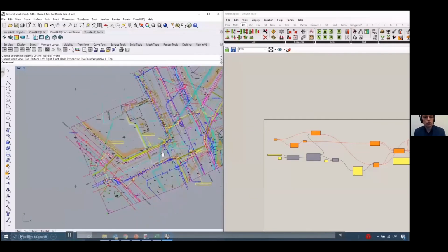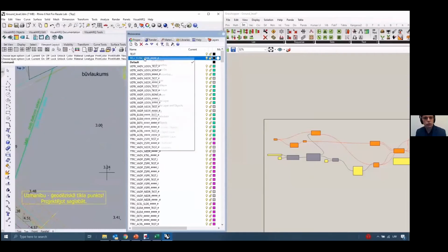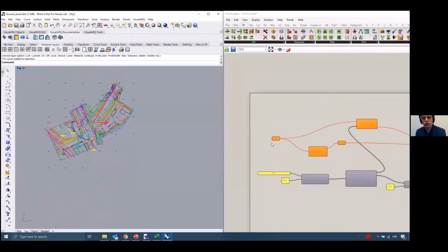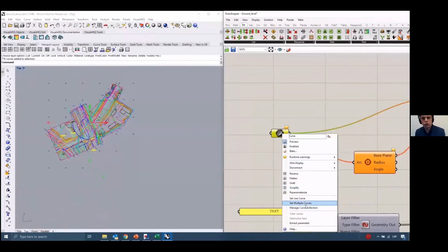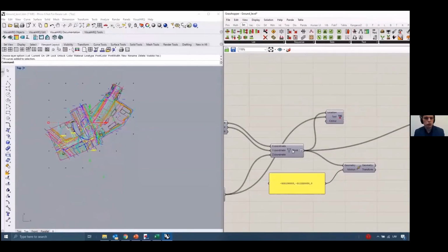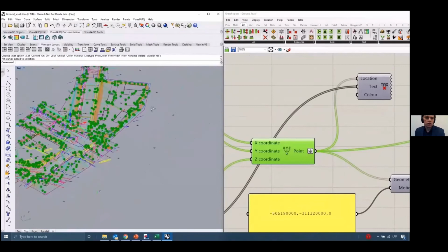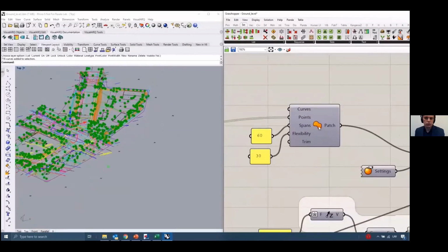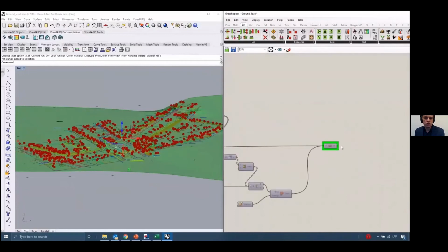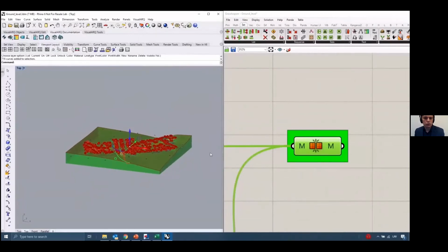As I said, you can use Grasshopper to generate all kinds of complex geometry. As you probably know, Tekla is not very good at dealing with non-standard shapes, some double curved surfaces and so on. So you can use Rhino and Grasshopper for that. In this example, I will generate the ground surface based on a 2D topography DWG file. I can read the point coordinates, and I will read the text attributes that are closest to each of the points. Through those points I generate the surface, and then from this surface I can extrude and get the 3D solid model.